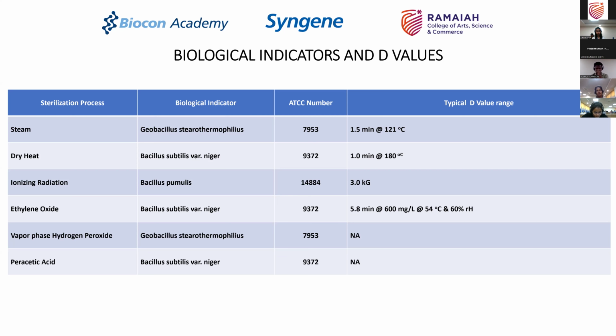When we discussed isolators, we covered vapor phase hydrogen peroxide, and isolators are one area where vapor phase hydrogen peroxide is used even today, I would say very broadly and industry wide, as the means of creating a decontamination within the isolated chambers.